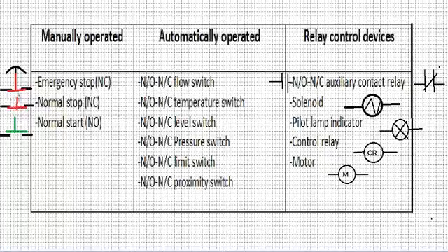And why do we have 2 types of stop? Well, systems typically will have 2 stops, one e-stop and one normal stop. They are both represented with red color. And then we have a normal start, which is normally open. Notice that the horizontal bars are open from the next parallel horizontal bar. So that's typically the way you're going to find them represented.